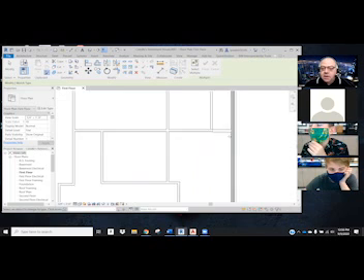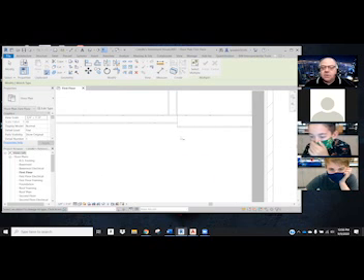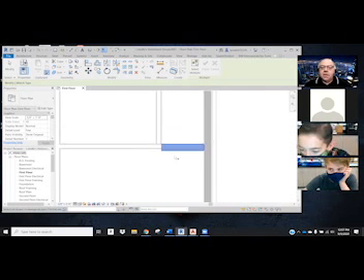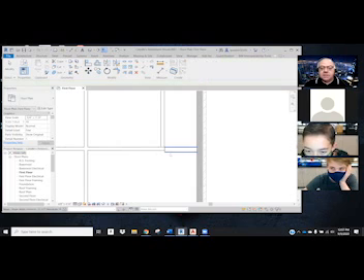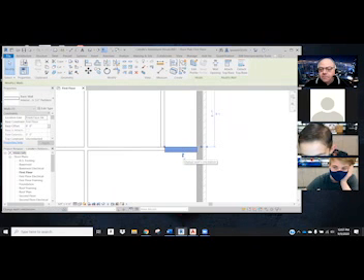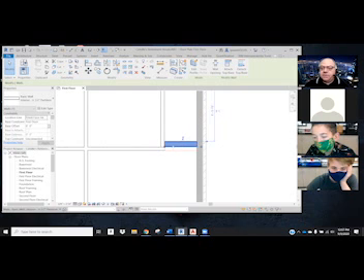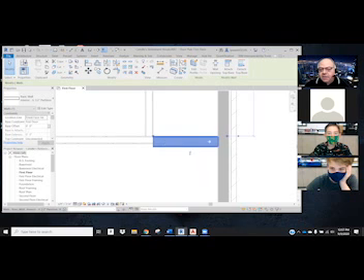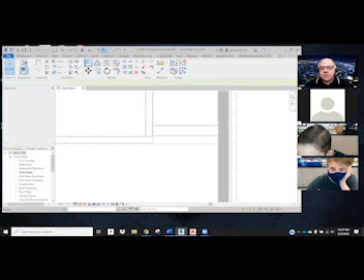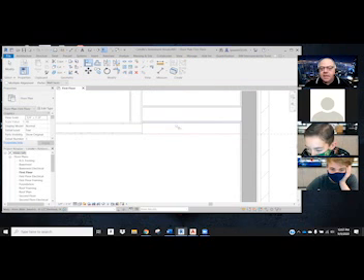So now this wall is thicker, but it's going the wrong way. Okay. So I'm going to escape out of the Match Properties. I'm going to select this wall, and I need to get out of Properties. Select this wall. There's an arrow there. I'm just going to flip it over. Oh, now it's way out of whack, but it's an easier fix this way than this way. So you see that red line goes underneath? It's hard to match it with the align when it's underneath. If I flip it over, then use the align tool, I can align that where it's supposed to be.